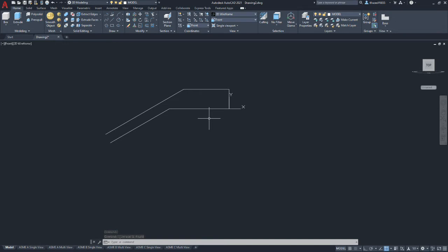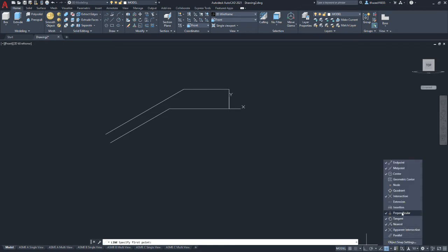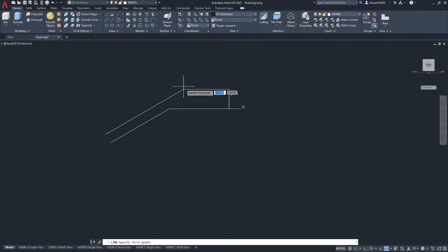Now we need to set the length of 8 inches. So the length of this is set off the top corner. We're going to use a line, and we're going to go over to object snaps and use perpendicular. So make sure perpendicular is selected. Actually, we're going to drag down until it snaps perpendicular to the line we drew. Okay, we just need that line, and we are now going to offset that line by 8 inches. Okay, now that we've offset by 8 inches, we've established the length of the part.